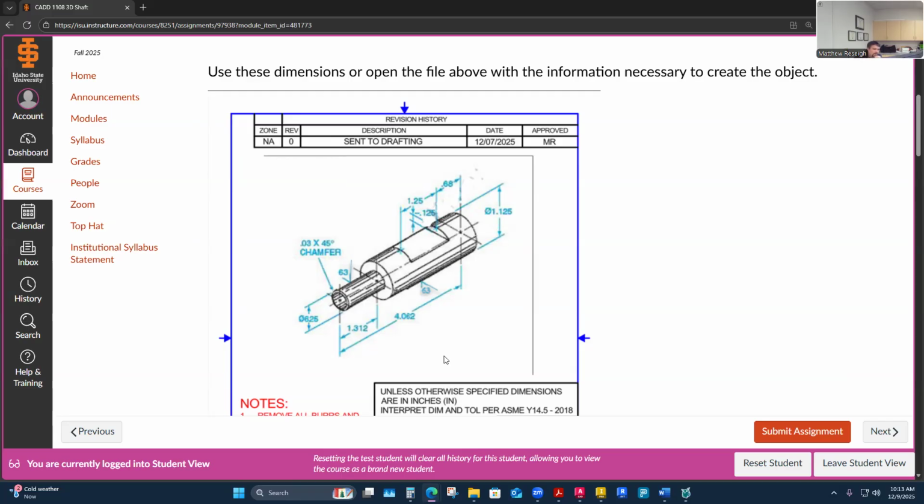it's going to work pretty well. Some of the details I will leave out, and some of them I will leave in. So a cut across like this, I'm not going to draw that detail in, because if I draw half the shaft with that in, it's going to revolve that cut as well. With a little bit of experience, I can say, well, I'm not going to do the cut until after I get the whole shaft, and then I'm going to cut across it and put in this feature of the shaft that has a flat spot in it. So all I'm really going to draw is the main small skinny section and then a wider section, a nice base foundation to start my shaft from, and then do any detail work secondary.